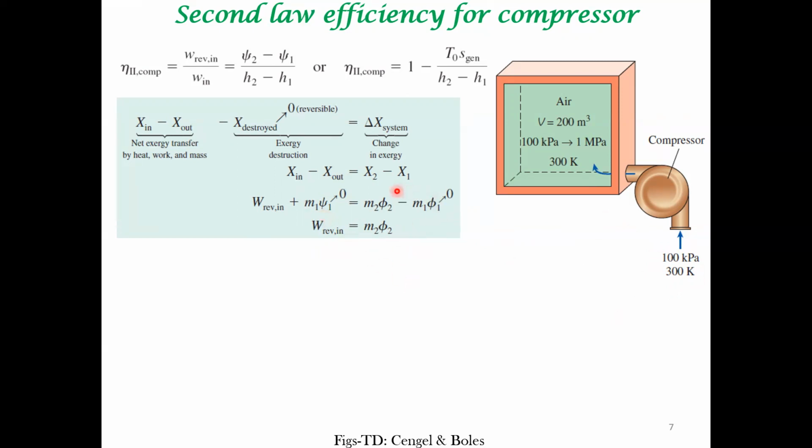This is the balance after you start pumping it. This is the initial exergy of the system. To begin with, it was a dead state, and then you put a certain amount of mass into the system. That's the exergy that is accumulated because of the compressed air filling up this enclosure.